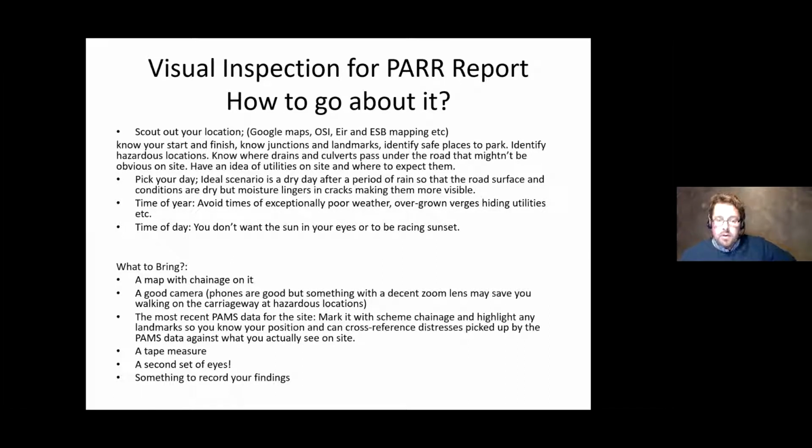The time of year is very, very critical. So for safety reasons and just for visibility reasons, you don't want to be working in exceptionally poor weather. But likewise, if you're going in the peak of summer and you've overgrown verges, they're going to be hiding your utilities. You're going to make life much more difficult. You mightn't be able to stand in safely, and be conscious as well that you don't want the sun in your eyes when you're taking photographs. Likewise, you don't want the sun in the eyes of drivers as they're approaching you. They mightn't see you. And you want to pick your time so that you're not battling to get home and get finished before sunset and you can't take any more photographs.